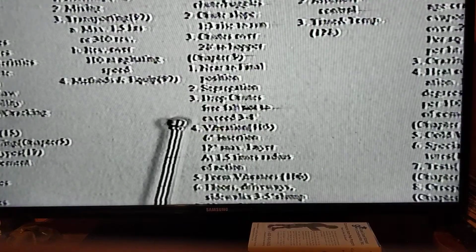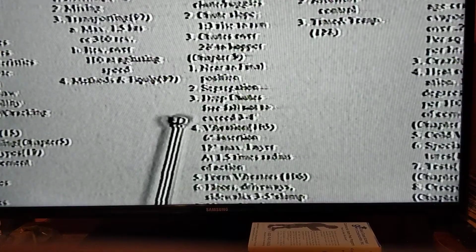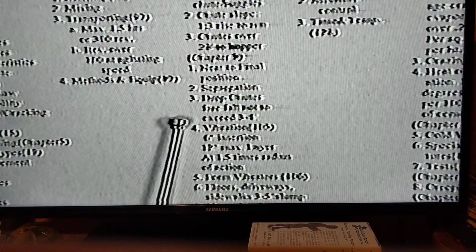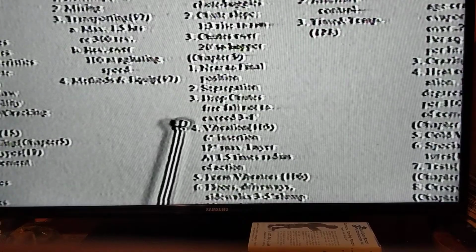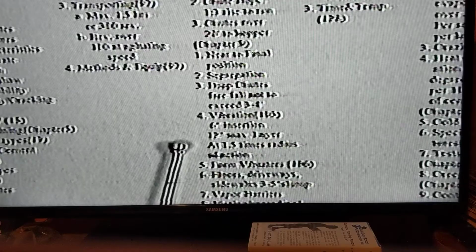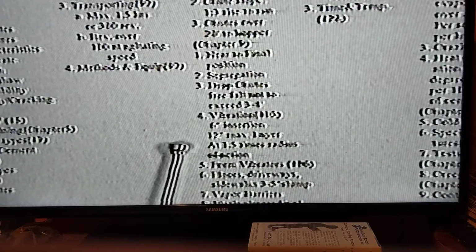Another issue that's important when dealing specifically with column work is the size of the aggregates. If you've got a bunch of pieces of rebar stuck in a column, you have to consider the idea that the concrete won't fit if the aggregates are too large. Another issue has to do with how do you make sure that the milkshake stays consistent. And one way you can do this is through vibration.